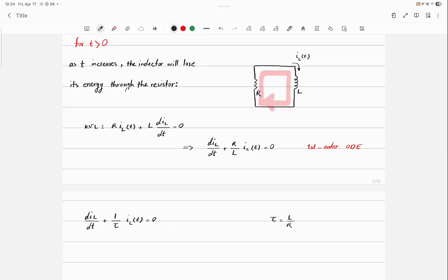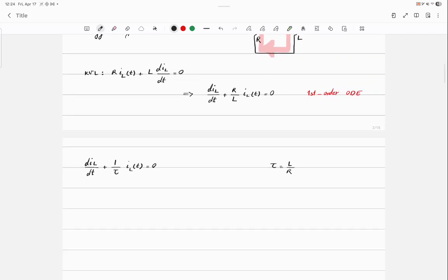Exponential. Okay? That's called guessing the answers to a differential equation. Because of the way the differential equation is, I can say that the answer to this is an exponential function. So how should I write the answer? IL(t) is equal to, I definitely have some exponential, and I just guess, for some reason unknown, that the exponential is in this form, e to the negative t over tau.